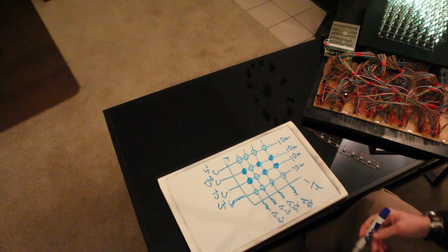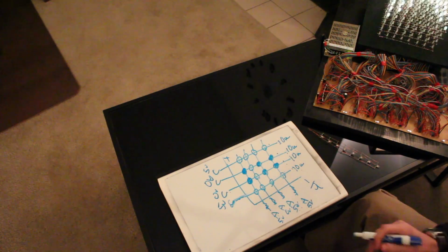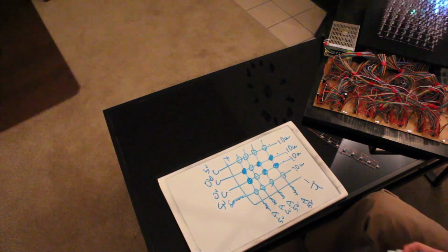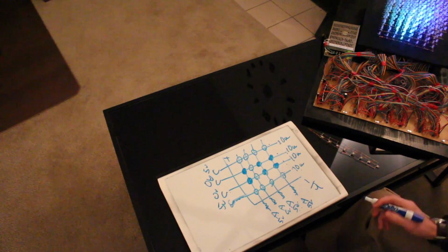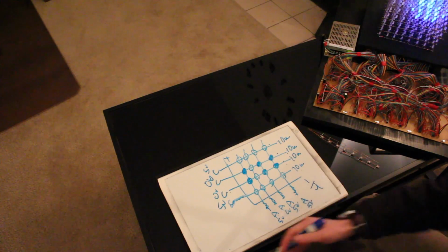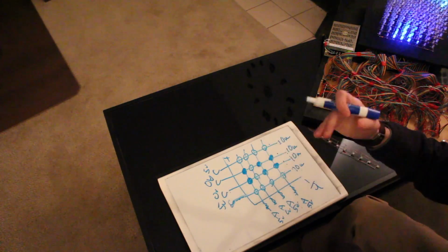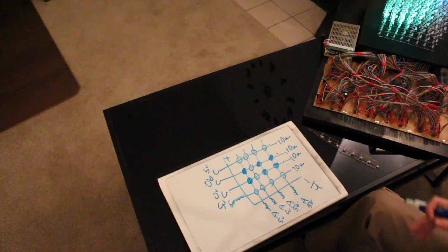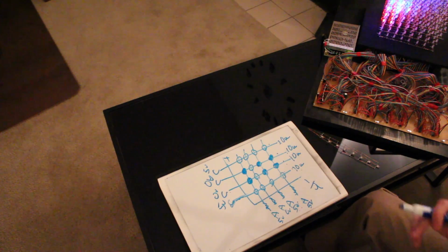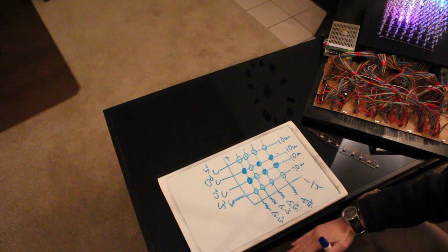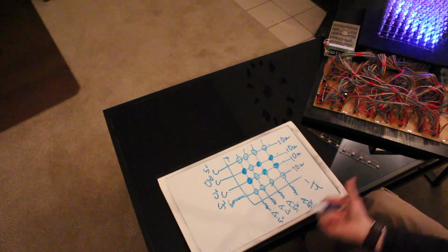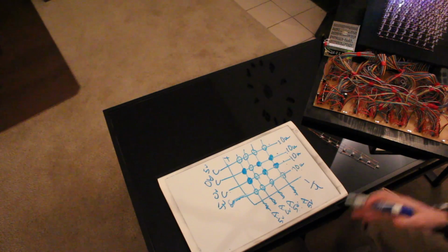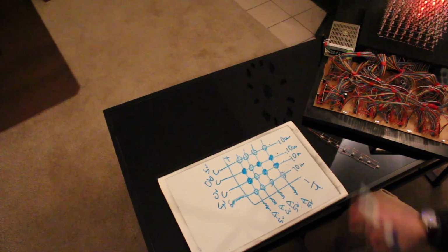Then that little rule in the data sheet that lets you pulse them a little harder doesn't apply, because it'll be there indefinitely. That's when you start having to play games with functional safety in the circuit, so that if for whatever reason your code hoses up on one row and doesn't go to the next one, you'll catch that somehow. You could use a watchdog timer, or as soon as my code's done going to the bottom, make a pin go high and then check that the pin goes high with a separate microcontroller or a reset, who knows. So just be aware of that.